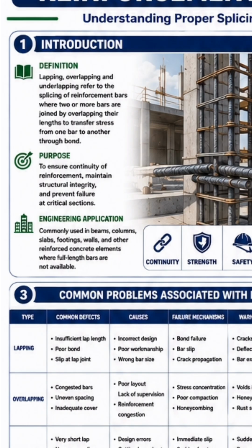So the purpose of lapping is to ensure continuity of reinforcement. You do lapping so that there will be continuity of reinforcement, then to maintain structural integrity. You do lapping so that you can ascertain the structural integrity of the structure and to prevent failure at critical sections.